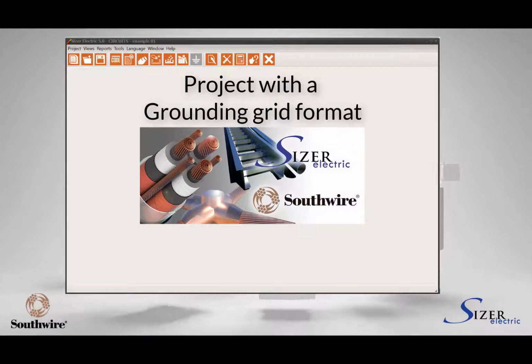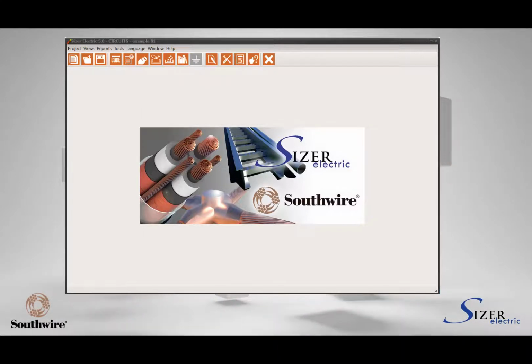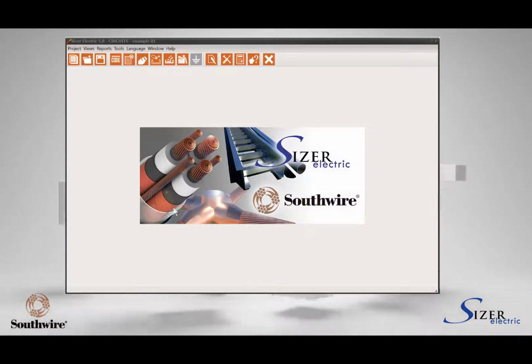The grounding grid design requires the creation of a specific project. This is because the file format of the grounding grid differs from the format used for conductors and cable trays and conduits. To create a grounding grid design project, select the option Project in the main menu, then select New.